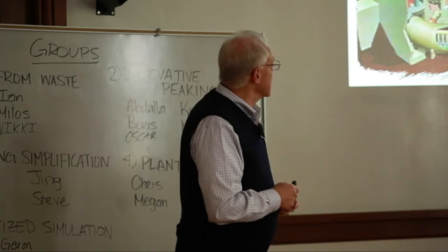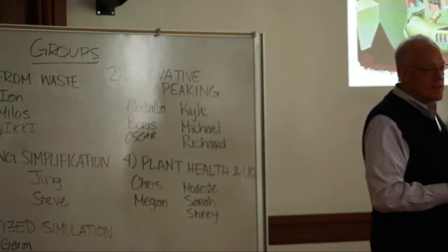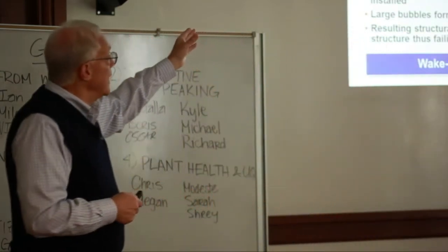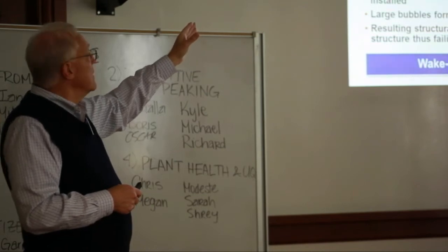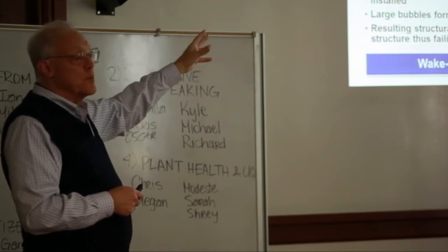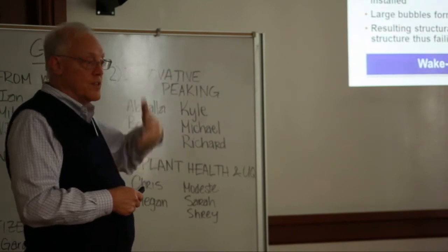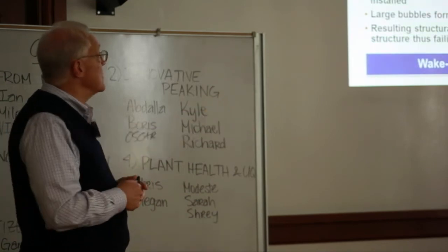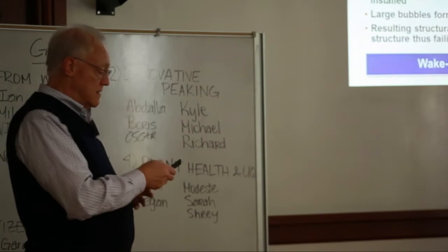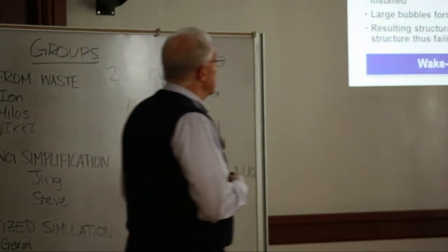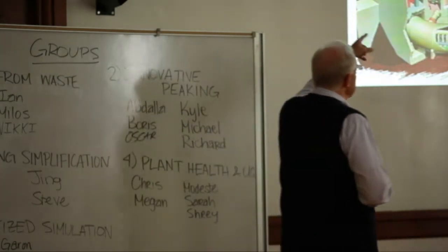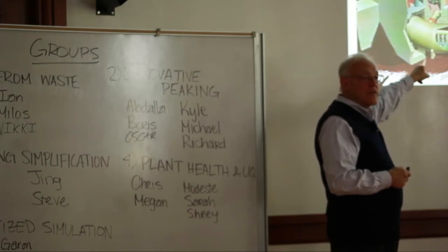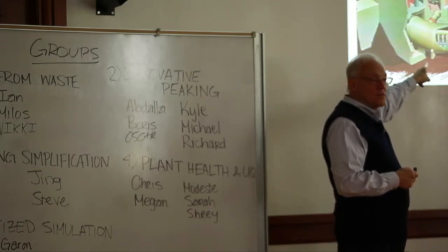Now what happened? Well, the way the BWR works, amongst other things, is the safety relief valves open on high pressure transients. And also in the case of a LOCA, they depressurize the primary system. That's the basic fundamental approach. I depressurize the primary system rather than leaving it at high pressure, which is the PWR approach. So I got two things. Now I got this line. I've got a line that goes from up in the upper areas here into this torus. So I dump this energy into the water pool, the suppression pool that's in this torus. That's the concept.